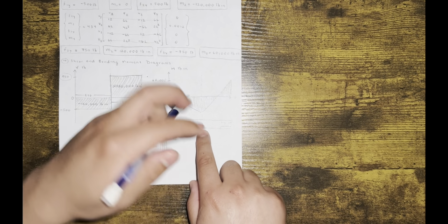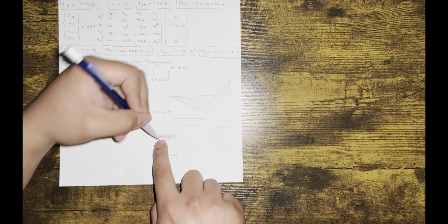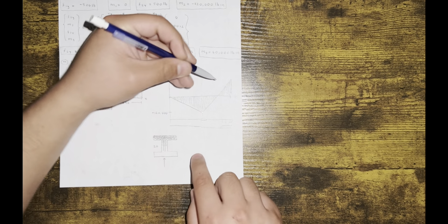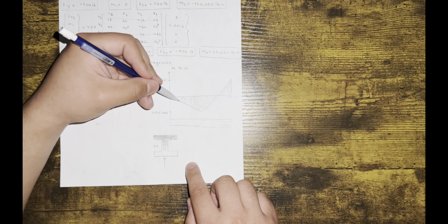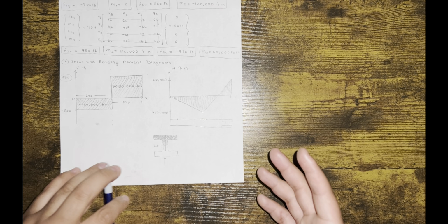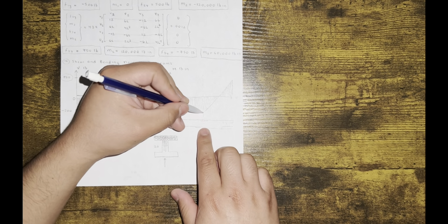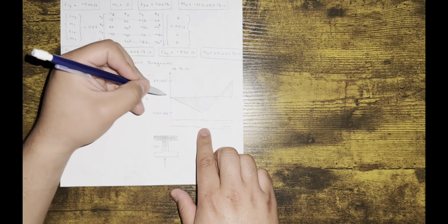Then right here, these caps, which are the top flanges of your beam, right? The top flanges here have to be able to withstand 120,000. Once you get here, these caps don't have to be as thick. And you might be thinking, well, how are you going to make a beam with a different cross section all around? And you're right. In some applications, it's better to just buy the whole beam. And as long as it withstands this section, it shouldn't be an issue.